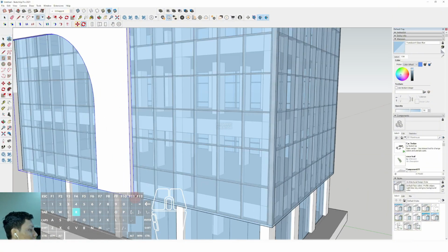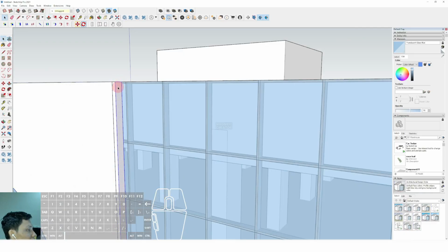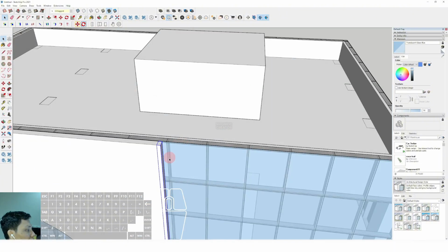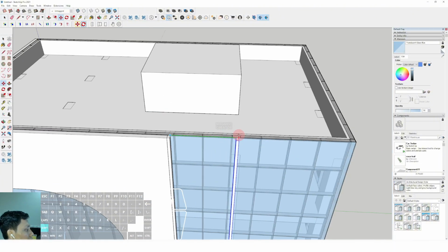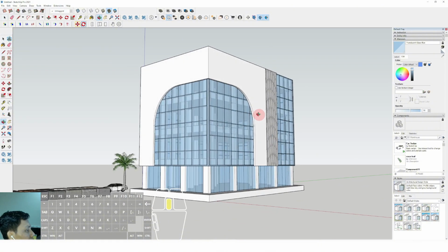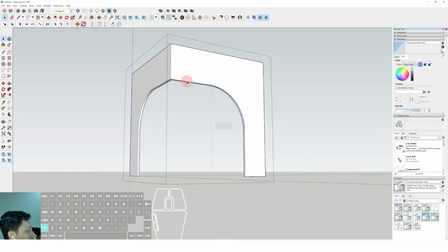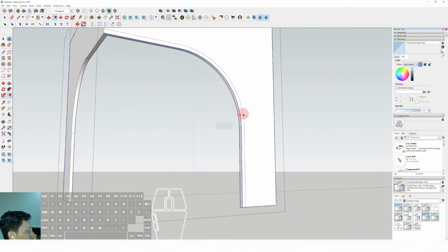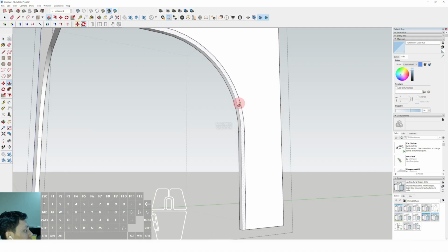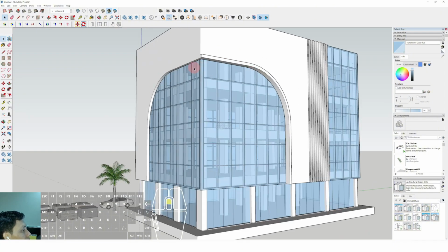Okay, just like this, and then now we can make the rectangle in here, and we can give a thickness of this rectangle, make component, create, and then we can select move, tap control, and place this position. Then we can type 10 slash and enter. Okay, and then now we can give a border. We can type 300. We can type 300 again, and also this one.